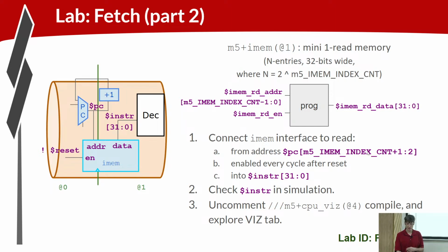So we're going to use that parameter to hook up the program counter, right? So that our code is properly parameterized if the size of the instruction memory changes. So we're going to hook up this IMEM read address to the PC, ignoring the lower 2 bits of the PC. So these ranges are the same, shifted by 2, right? This is the index minus 1, this is the index plus 1. That's the extra 2 bits.